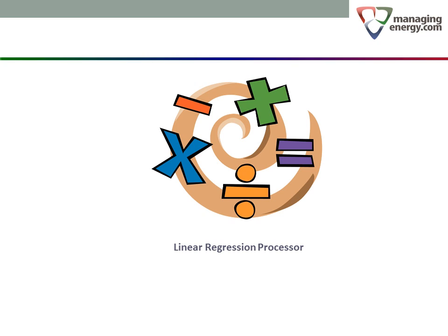The next obvious question is, how are these models created? Where do the constants T, H, and C come from? They are calculated using a statistical process called multivariate linear regression. You feed some historical meter readings into software along with the corresponding outdoor temperature conditions, and it produces the three constants for you. The linear regression software finds the formula that most closely matches the meter readings you have fed in. Suppose your organization has decreed 2009 as your energy base year. You want to measure future energy performance against 2009, correcting for weather differences. To do that, you need to create a baseline model.